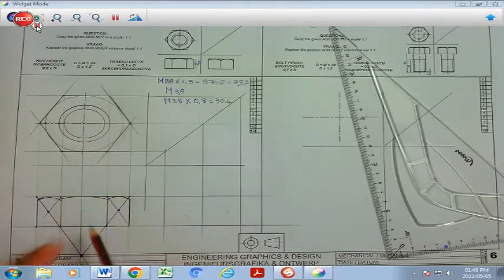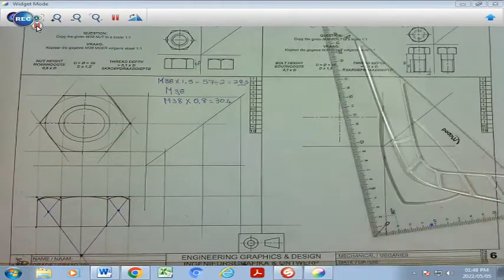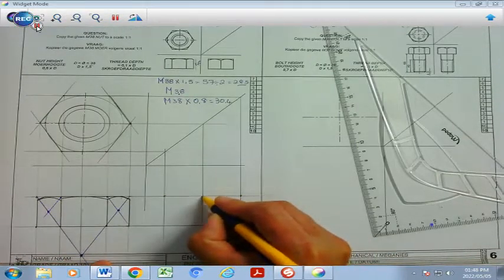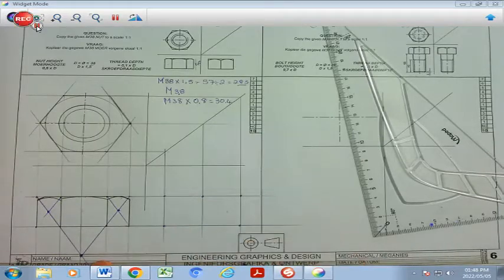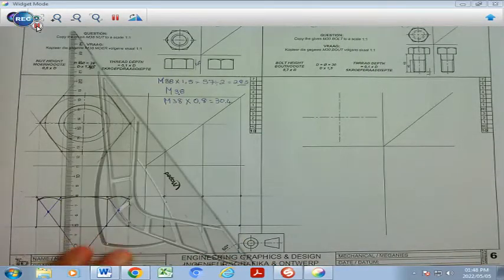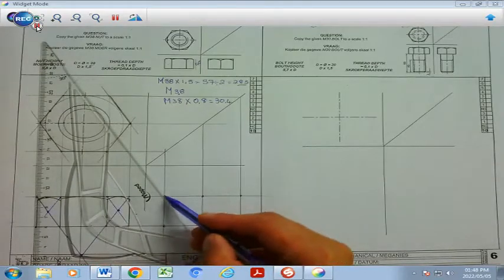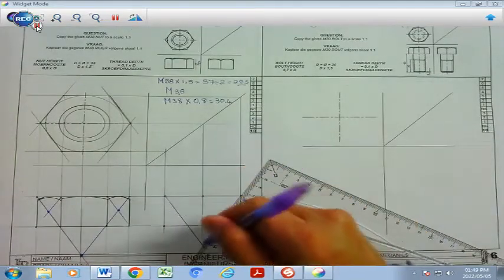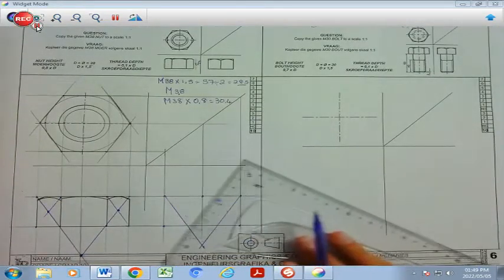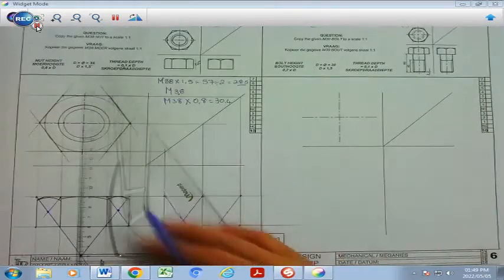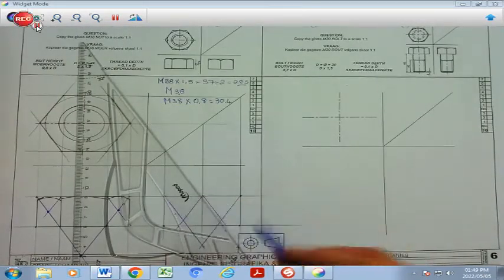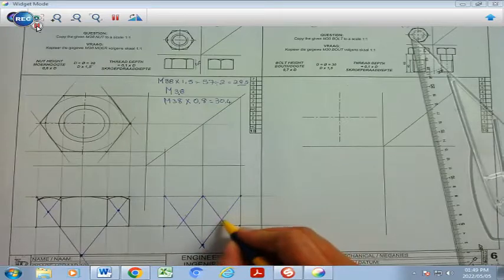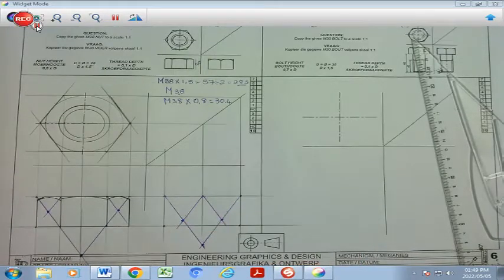The same procedure will be followed here with the 60-degree lines in purple, and that will come from these specific points, that point over there and that point over there. This is my middle, this is my bottom points here. So let me do the same. From the top corners I will project 60-degree lines down both sides, and they will meet in the center, as you can see here. I will also do 60-degree lines from my middle point both sides, and I will repeat that process. I now have created this point over here, that point over there, and that point over there.